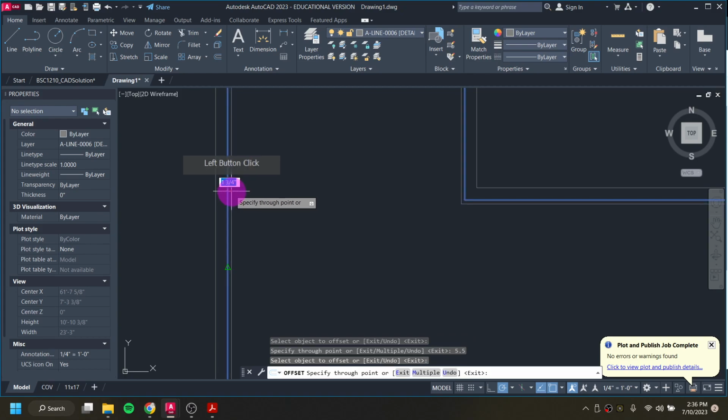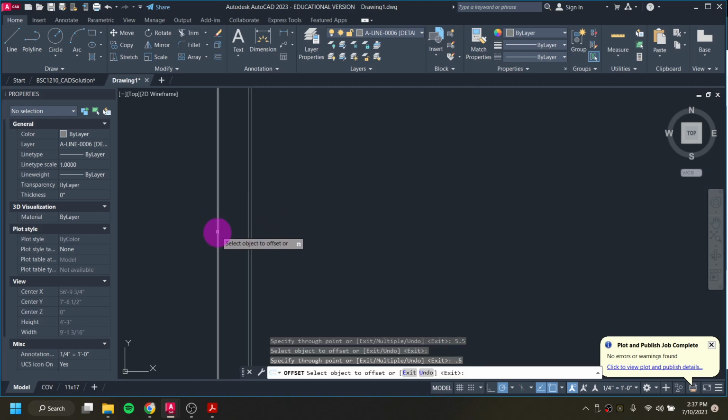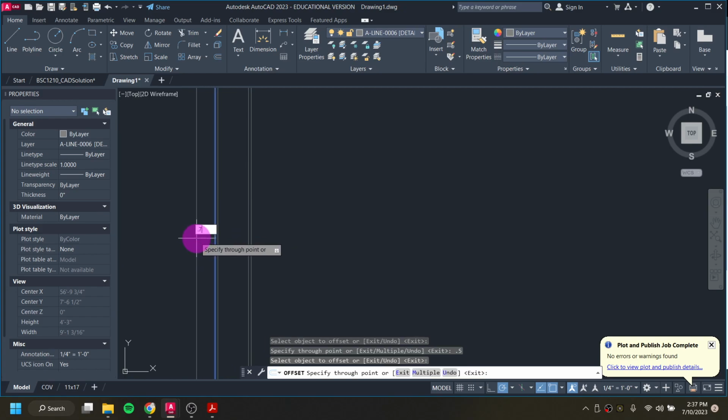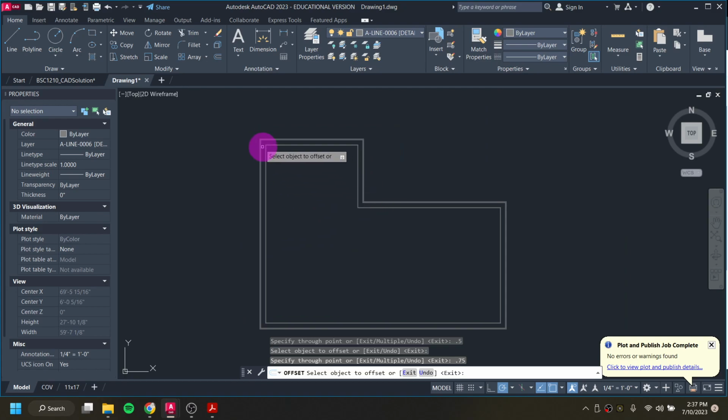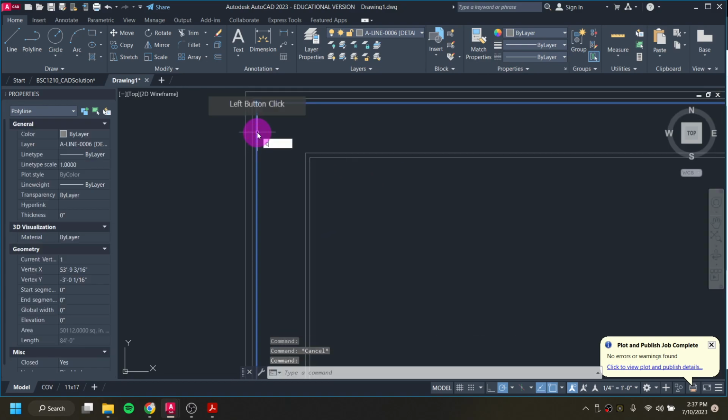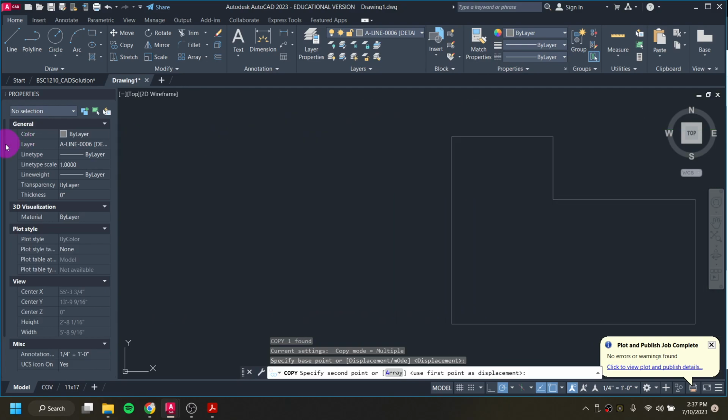I'm going to bring it in again a 1/2 inch, so 0.5, enter. Then I'll go back to my original line and bring that out a 1/2 inch for my sheathing, and out 3/4 of an inch, or 0.75, for my siding. So I've put all of those layers into the building without a lot of effort. Let me make a copy of this over to the side here.